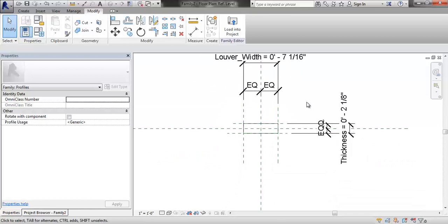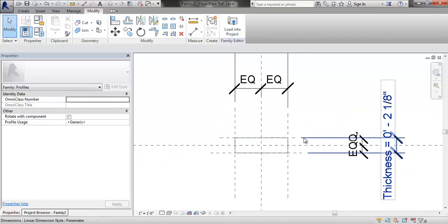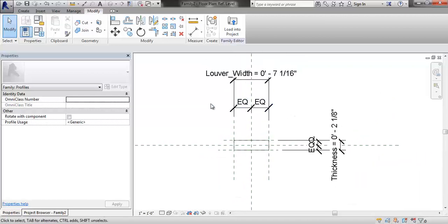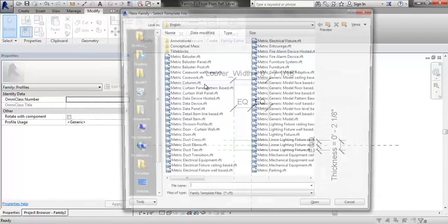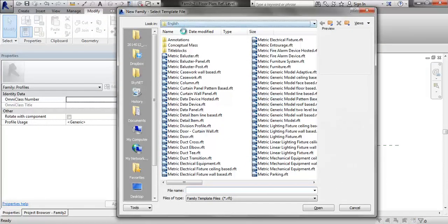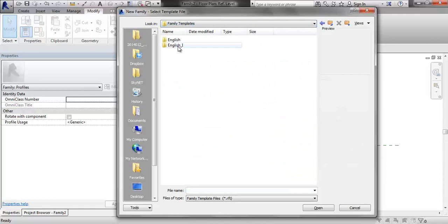The reason why rotation at this point is not going to work is because of the embedded logic, right? So I would have to build a third tier of data, right? So I'd have to do a profile family into another profile family to get it to rotate, and then load that one in. So let's give it a shot. Why not? Hell with it. So I'm going to do a new family, and then profile. So we'll immediately begin learning about nesting from this then.